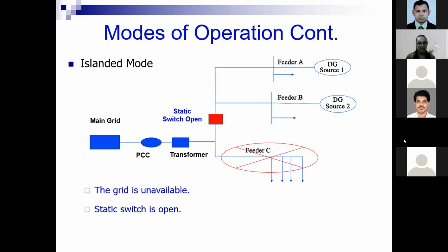of the microgrid. However, even in the islanded operation, with the limited generation capacity and the heavy reliance on intermittent energy resources, it is required to minimize the demand and supply deficit or mismatch and maintain an uninterrupted power supply to the critical loads. Therefore, sometimes it may be required to set up a priority order for catering loads to ensure that the important loads will get an uninterrupted power supply.